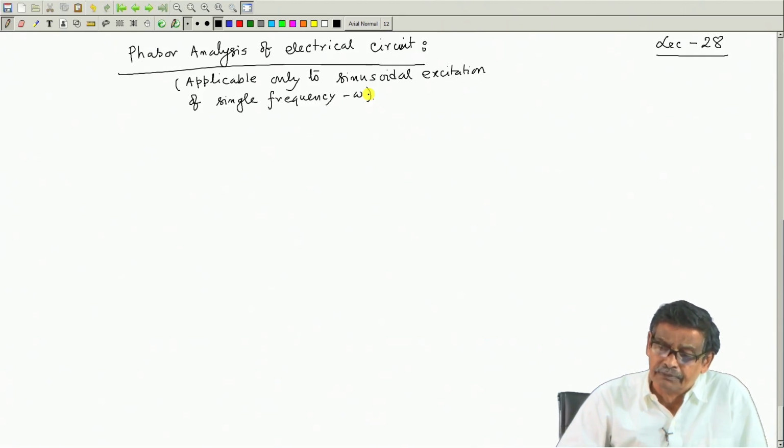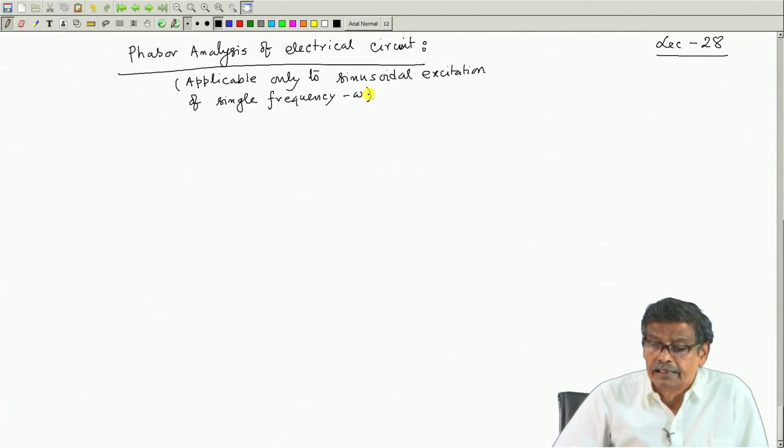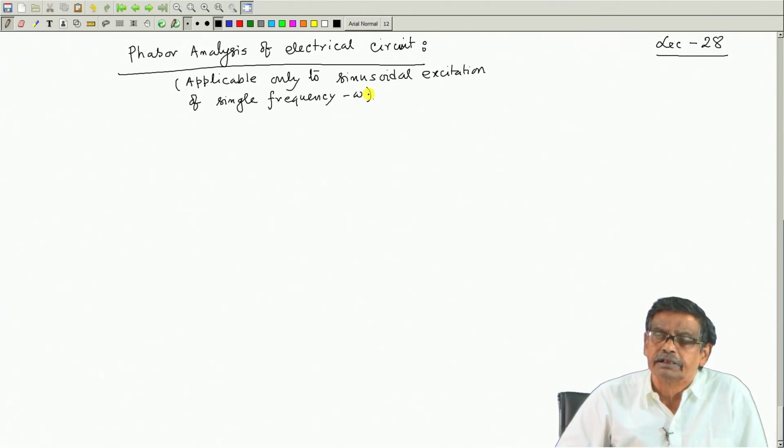will be born, they will die after some time depending upon the time constant of the circuit. How long that transient will last is decided by that, but in any way, for all practical purposes they will eventually die down, and only the solution due to forcing function is of concern after certain time, after you have switched on the circuit, and then steady state condition prevails, and that steady state solution is nothing but the solution due to forcing function that we have seen earlier.